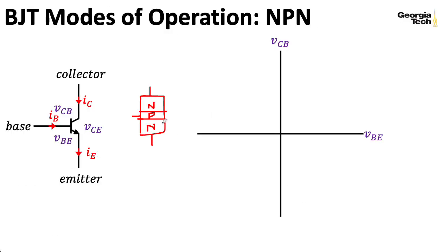devices. So we do have two p-n junctions here, but this sadly will lead people to draw this incredibly misleading diagram. They'll draw a couple of diodes in a schematic that looks a little something like this. They'll put the base here, they'll put the collector here, they'll put the emitter here. And I see what they're trying to do. They're trying to indicate the junctions, but this is extremely misleading. It gives you the impression that you can build a transistor by just sticking two diodes together.